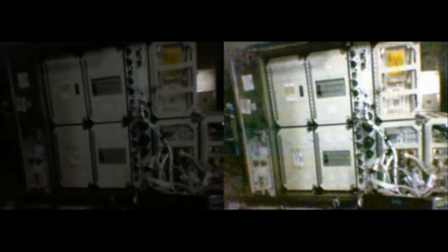We were having a bit of a problem with the sphere that day with it resetting, and it had to do with the IR mechanism I was talking about being jammed by the lights that are on station there. It turns out when a fluorescent light begins malfunctioning, it emits a lot in the IR spectrum. And so we basically had to turn the lights way down.